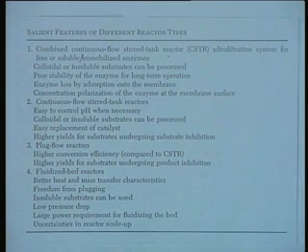Now, in the case of CSTR, the favorable point, as I mentioned, was that for reactions which are substrate inhibited, CSTR is a desirable feature. The other desirable feature of CSTR is that it can be used wherever pH control is required, because it provides you an open configuration in which pH monitoring and control both can be exercised, which is very difficult in the case of a plug flow reactor.